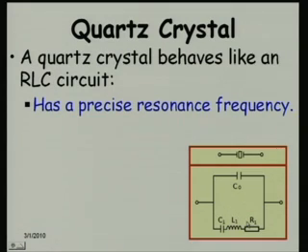Sir, what is C0? These are some capacitance values, C0, C1 are capacitance, L1 is an inductance, R1 is a resistance. Sir, this RLC is the bottom one. No, this entire thing is a RLC circuit. Okay, this is the equivalent of this. It's a RLC circuit. It will have its own resonance frequency, right. So, how to model this in this form, let us not worry about it, but this is a model of this. Let us assume that there is a capacitance here across, and there is also capacitance, inductance, resistance involved here.